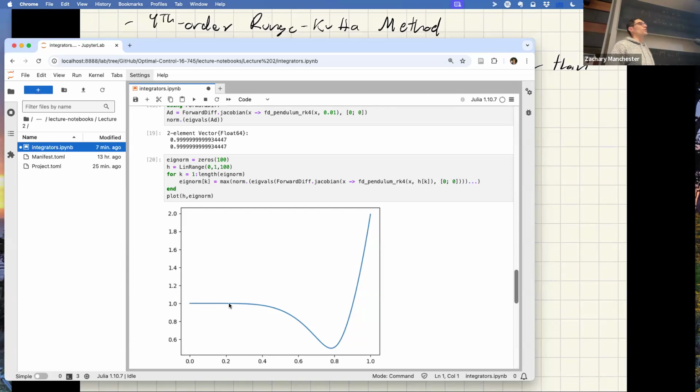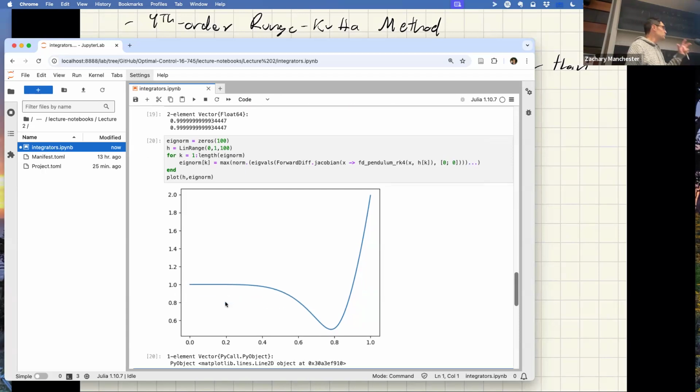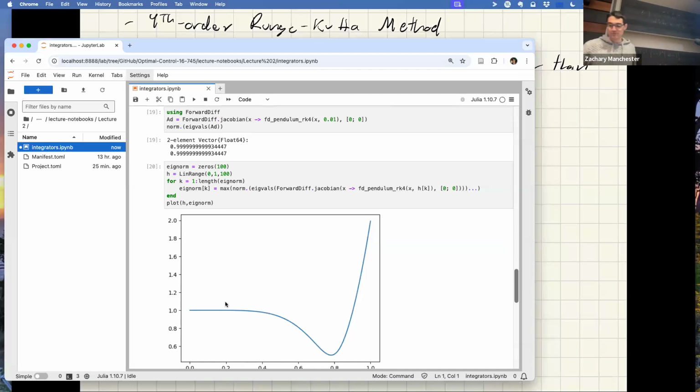Yeah, pretty much. At that point, you're basically undersampling the dynamics and bad stuff's going to happen no matter what. But the message here is this thing's really solid for reasonable time steps though, right? Like this is 5 hertz. That's stupidly big steps, and it's still pretty solid. So this should be your first go-to move, essentially, if you're going to do simulation.